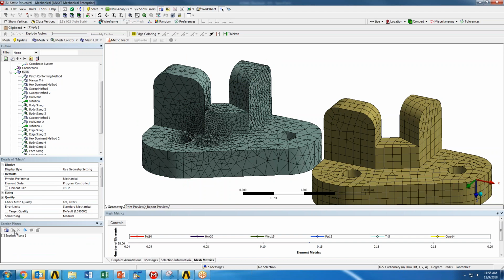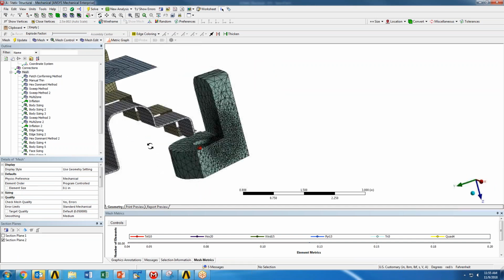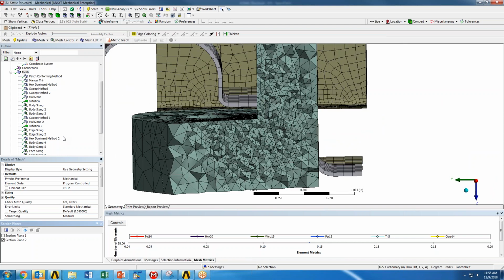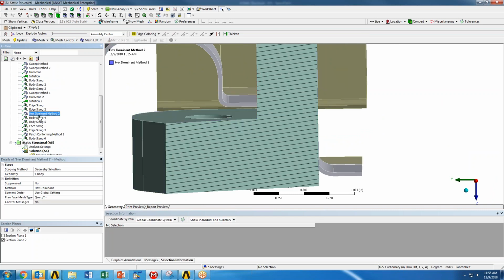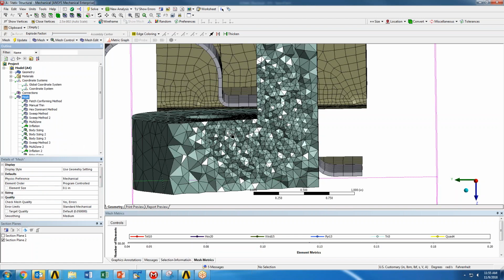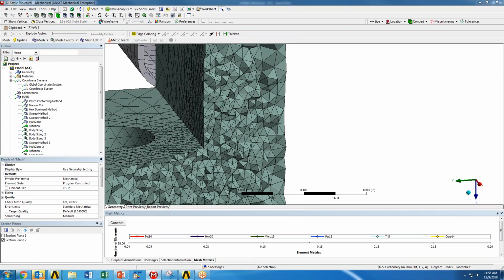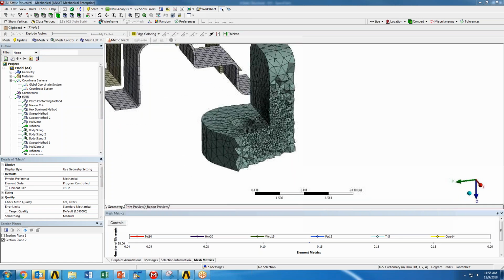And then we can see, if I take a section of this sphere, I'm actually going to show the elements. You can see everywhere in that sphere has been refined, right? And you could just refine, it's not going to show both at the same time, you could just refine the surface, right? And then you get slow expansion out until it is at the default element size. It's just wherever you want to see, right? Here, if I'm trying to capture, let's say there was a fillet here and I want to see how far that stress concentration propagates in the material, I would probably do a sphere of influence, likely not this size, but that would capture refining the elements through the body rather than just on a surface.